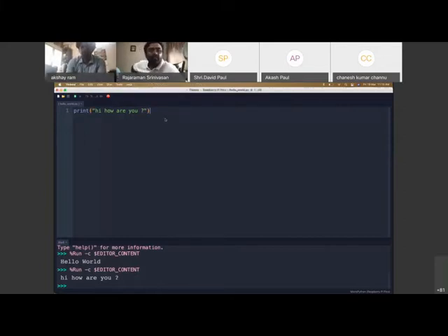Okay, first we will set up the code to run on the Pi Pico. On the bottom right corner, you can see that my Thonny is set to MicroPython Raspberry Pi Pico. Yours might have a different value. It might be running the Python installed on your system.